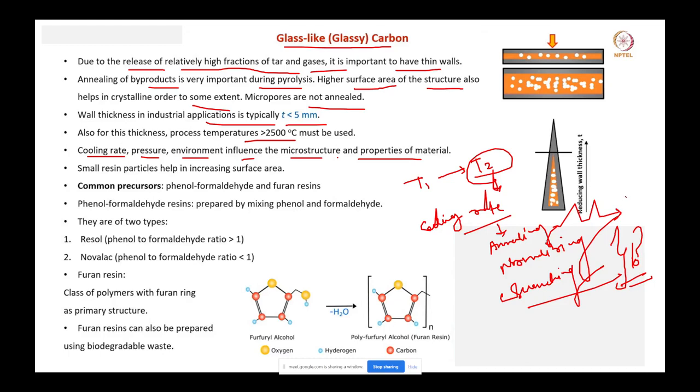In annealing treatment, basically we convert austenite to pearlite structure by slow cooling after heating. There is a slow cooling rate. Whereas in normalizing, the cooling rate is a bit higher, and a fine pearlite structure is formed.